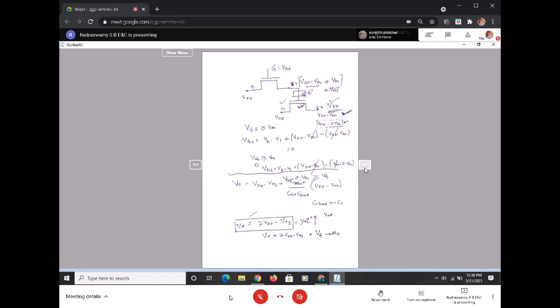Okay. And now the maximum output voltage it can go to is something like VDD. If I take, what is my VGS basically now? It is again VG minus VS. VG is at Vx, that is VDD minus VT3, minus VS, which is VDD. So it is still VDD minus VT3. And this VGS, is it greater than VTH or not?